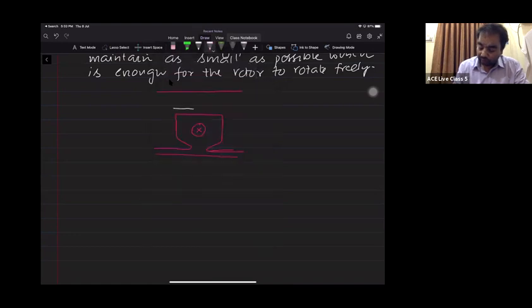So you can see here, in this 10 mm path, one flux line will definitely flow. There is no doubt. But when you are approaching the air gap, you can see this distance is decreased. Let us consider if this is 10 mm, this is 5 mm. So when compared to 10 mm, the 5 mm is still offering low reluctance.